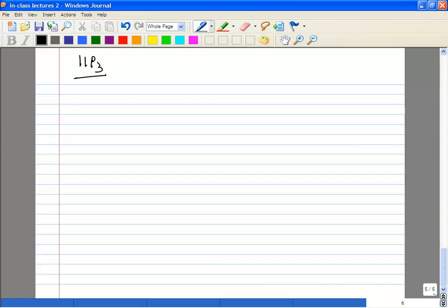Okay, so how do you calculate this? What we'll do is, it's defined as the extrapolated power where the power of the fundamental becomes equal to the power of the third order intermodulation product. Okay, so let's try to plot it on a log plot.